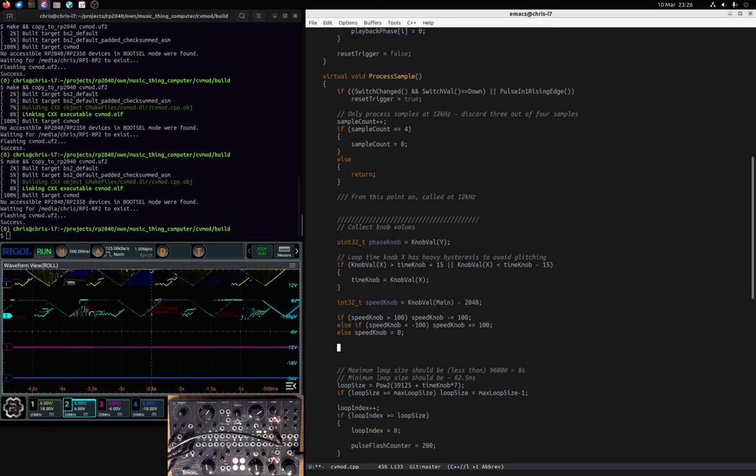So I think, so the ends of the knob travel are not, contrary to what early documentation suggested, the knob values in computer card are not guaranteed to reach the end points 0 and 4095. It appears on most systems as though they go to 4095, but they don't reach 0. But for this, I think I do want to sort of add dead zones at the ends as well to clamp the values to a known value.